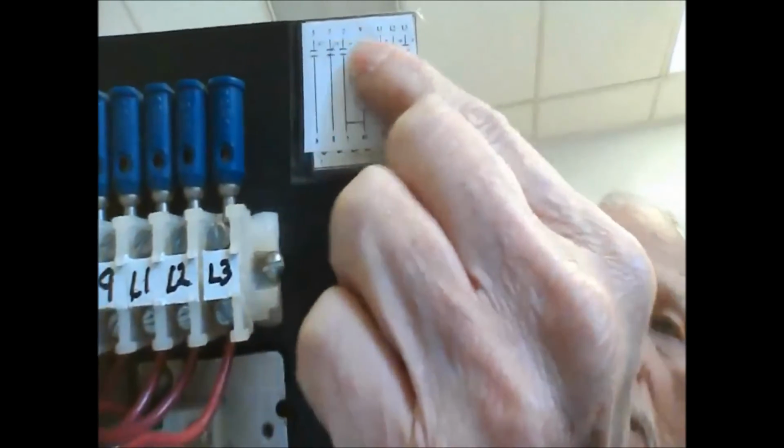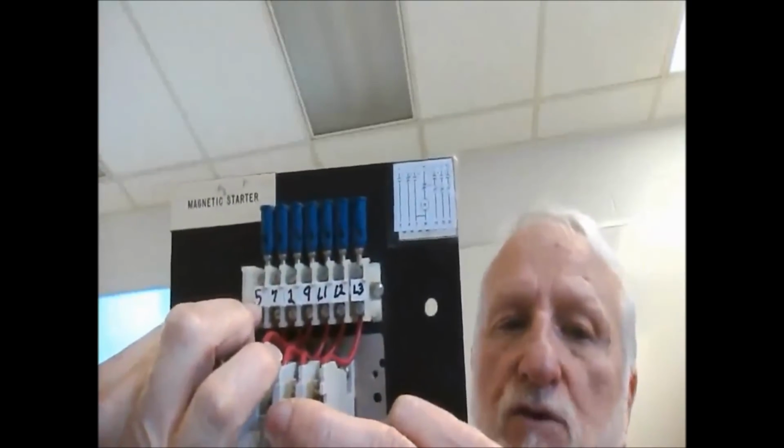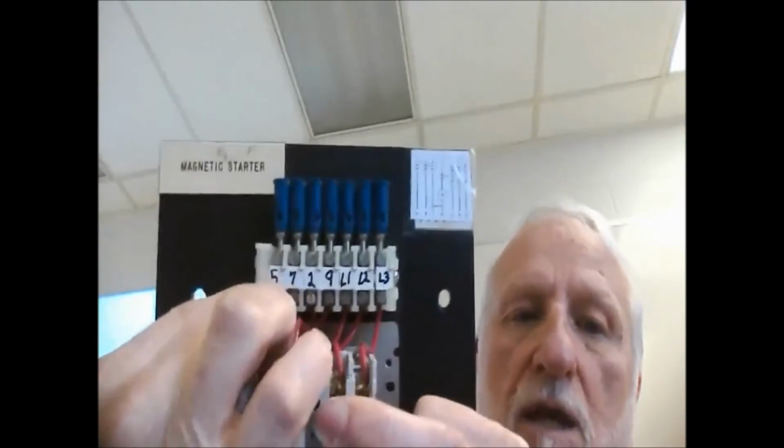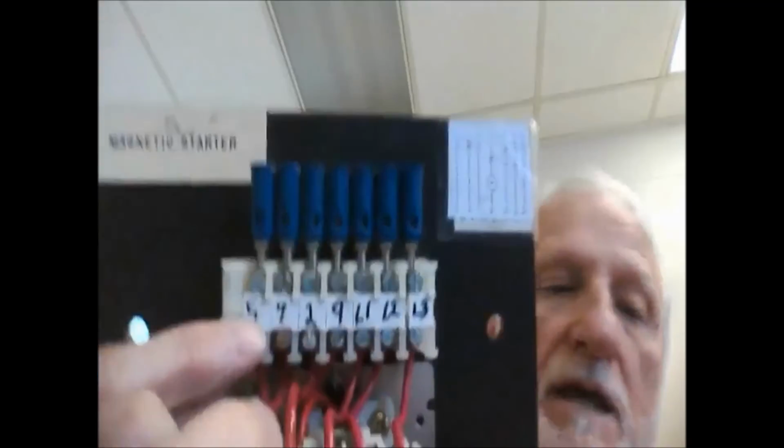So this guy here has 6 contacts on it. But up above this are these little numbers. These are called manufacturer numbers. And now what we've done is we've come back and we've transposed up here on our terminal board the true manufacturer number. So these are the manufacturer's numbers. So this would be terminal number 5. That makes sense? And then I can come up here and look at this diagram, and I could find terminal 5. So there's terminal 5 right there.